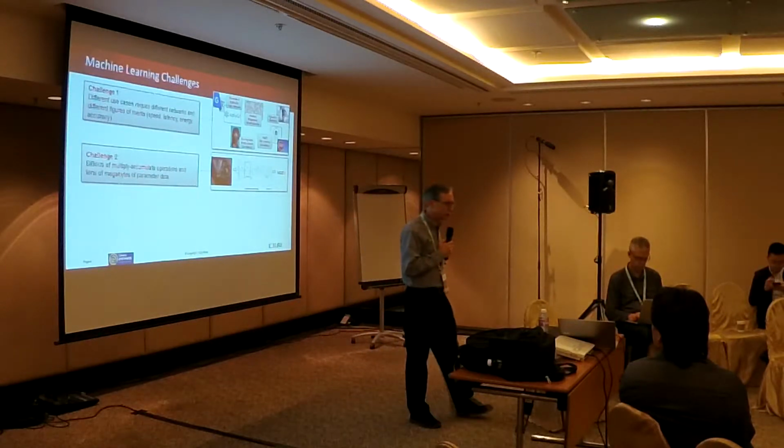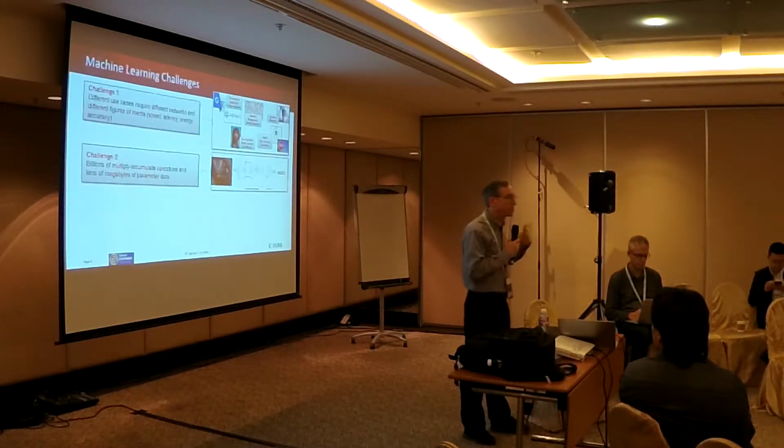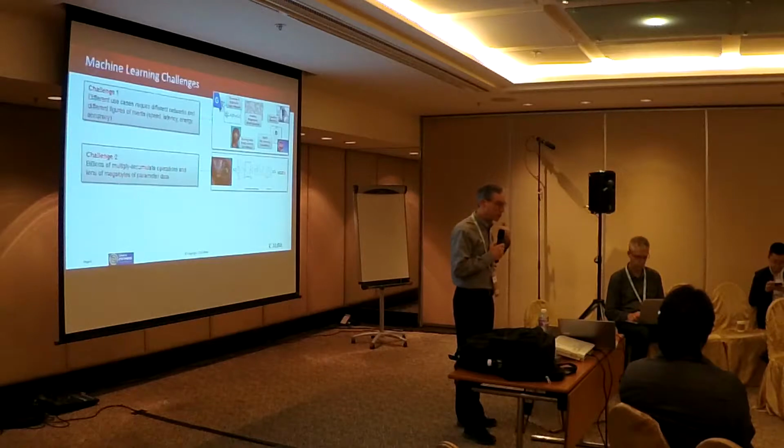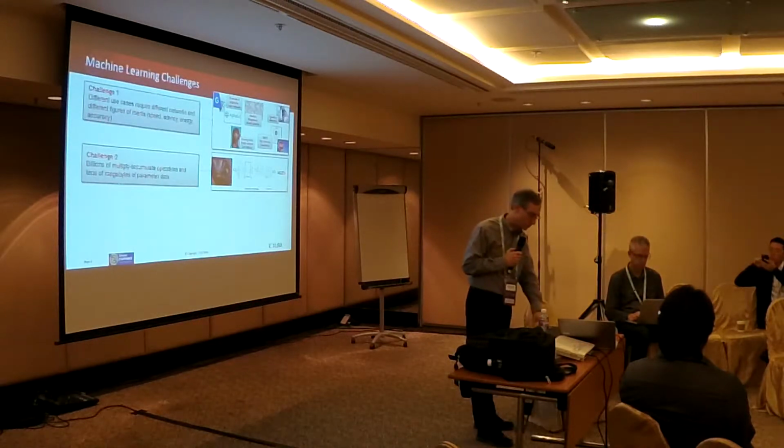And one of the other challenges is, if you go back to what I mentioned earlier, every single input to the neuron requires a weighting factor and a threshold value. You have to apply these in some manner. And if you're doing a typical computer application, and you're running software, that means you're constantly pulling this data in from DDR, so you're talking about moving megabytes of this parameter data as quickly as you can in order to do these multiply and accumulate operations. It can be very taxing on your memory systems and bandwidth in your processor system, and obviously that type of bandwidth also consumes power.